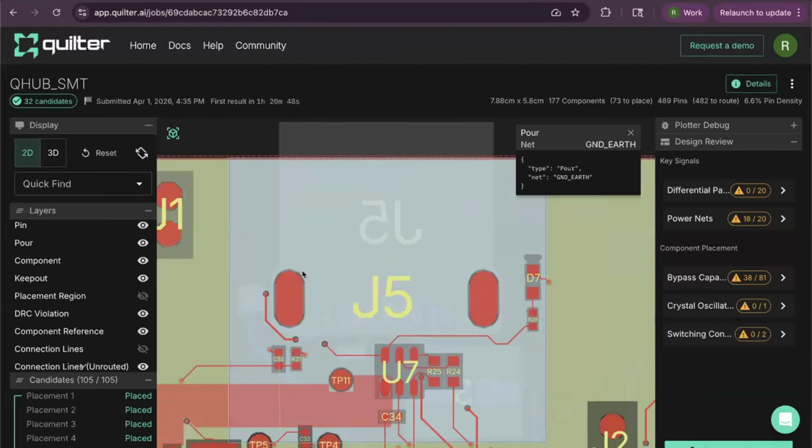It helps with a few designs. It is, as you all probably know, dangerous to use. It is definitely creating split grounds. Use with care. We're not going to default it onto anything. But with placement regions like this, if you've got components that need to bridge those ground references, like opto-isolators or whatever, you just pre-place them along the edge of that region, and then it works perfectly, exactly the way you expect.